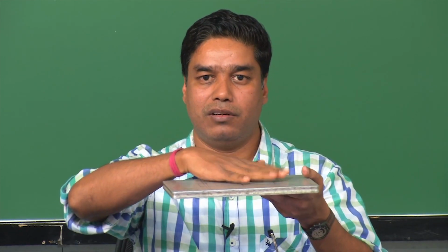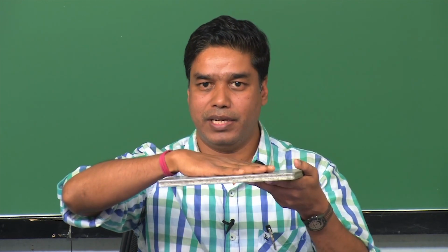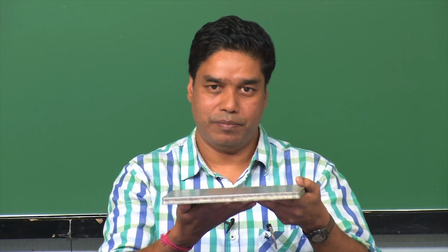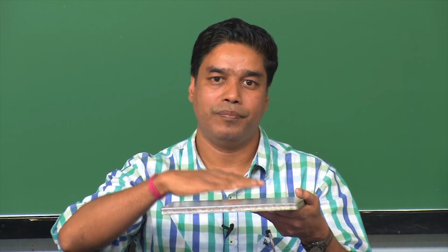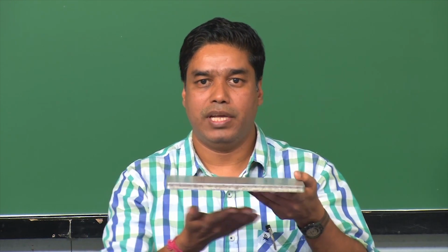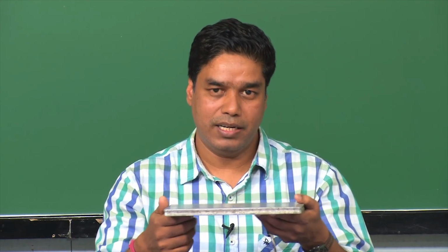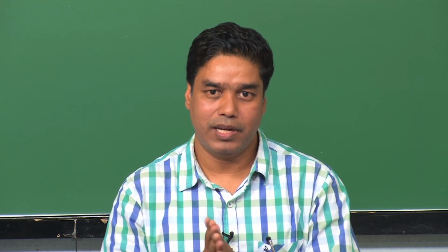Then on this the sample is kept on the top surface. So, right below the sample you have the intensifying screen and then the film. If you remember, we also discussed that the intensifying screen has to be in between the sample and the film, and it should also be there on the bottom surface, so that the backscattered radiation can be addressed. So, this is one aspect of exposure, as to how to load the film for a particular exposure.